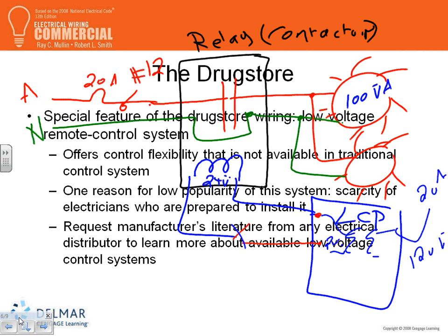You close the switch, you energize the 24 volt coil. When you energize the coil, it pushes these contacts to close, and then the light will go on. And that switch, guys, looks exactly like this switch, except it's a low voltage switch. Literally, low voltage. What does a low voltage switch mean? You're bringing 24 volt to it.